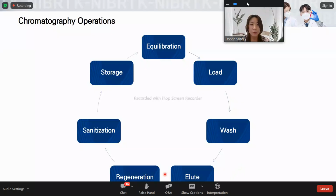Next, elute. During elution, we add a special buffer that helps to release the target product from the resin, collecting it in pure form. This buffer changes the conditions within the column to favor the release of the target molecule.